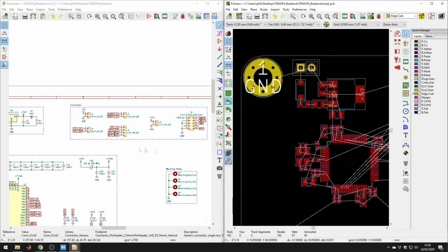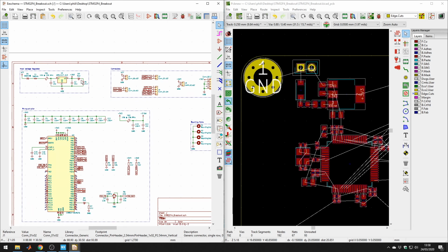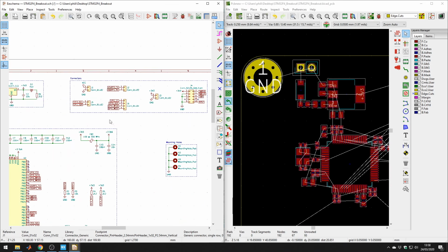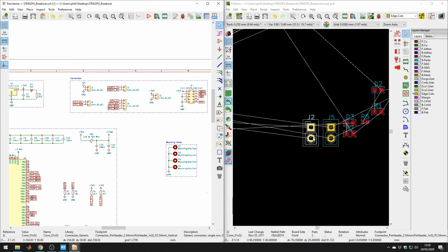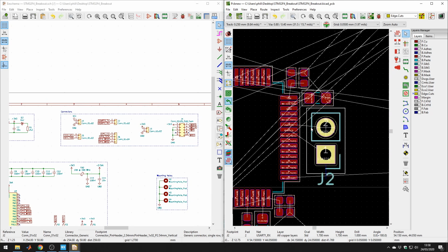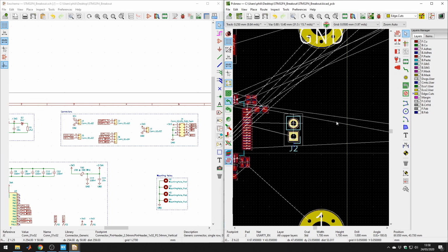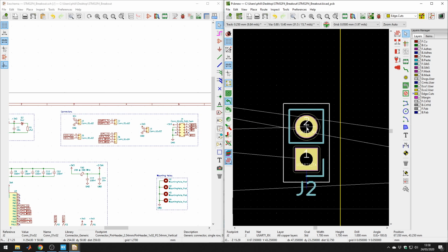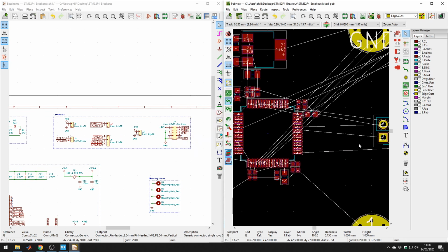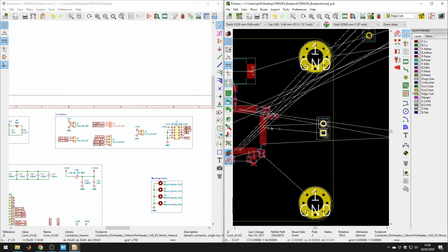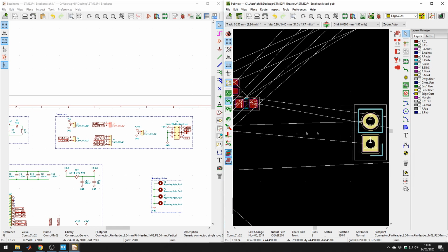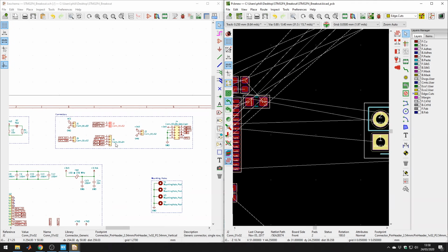Okay. Next up, okay, indicator diode, that's not important. We can do that fairly close to the end. Okay, what about these other headers and connectors here? So UART is on this side, so let's put the connector on this side, somewhere around here. And you see I rotated the connector so that there are not going to be any crossing air wires, because then you'll have to use vias, and that's completely ridiculous because we have very straight connections here.